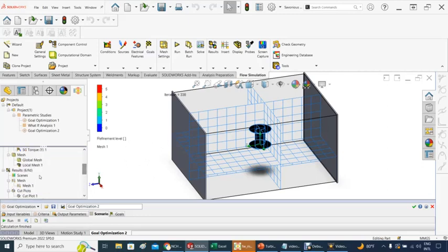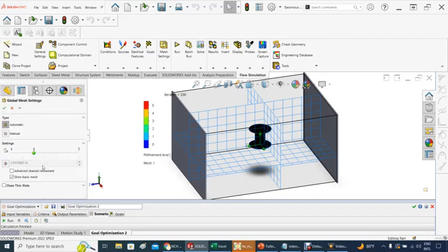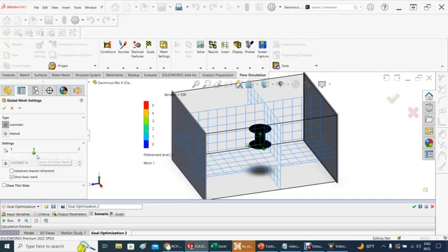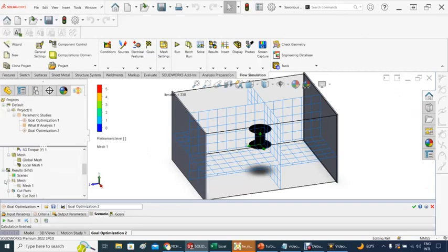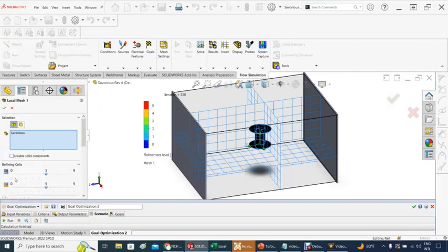So let me show you here the global mesh. Let's see, edit definition. You see, not much there. It's about 3. That's all I'm using. If you increase it to somewhere here, that will take a while. On the other hand, the other thing that I did, in order to get results that I start to believe, was with the local mesh, where I increased that local mesh from 0 in both to 5. You see, you can still do better.